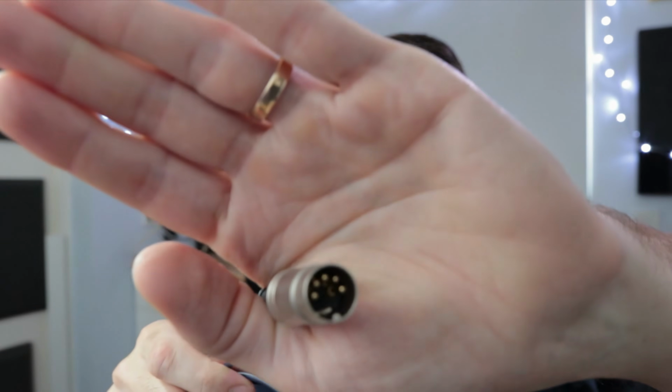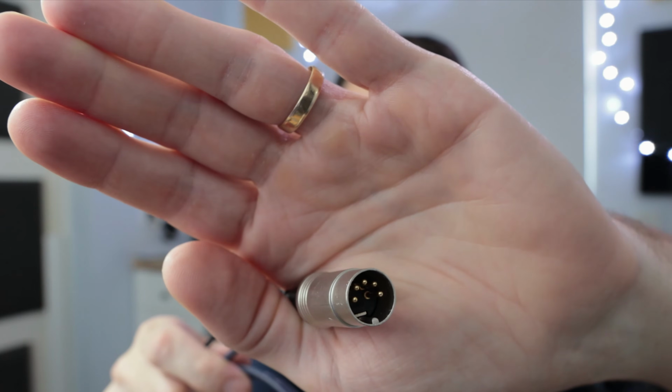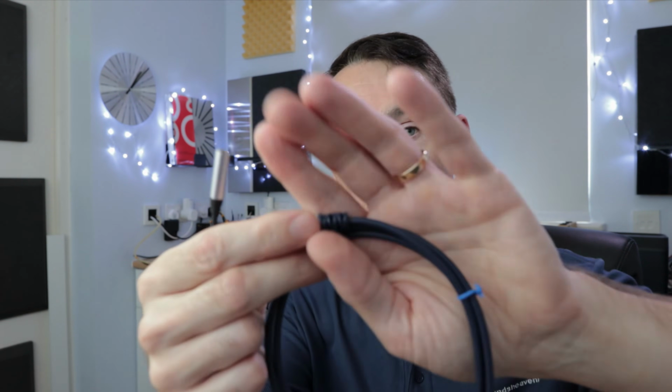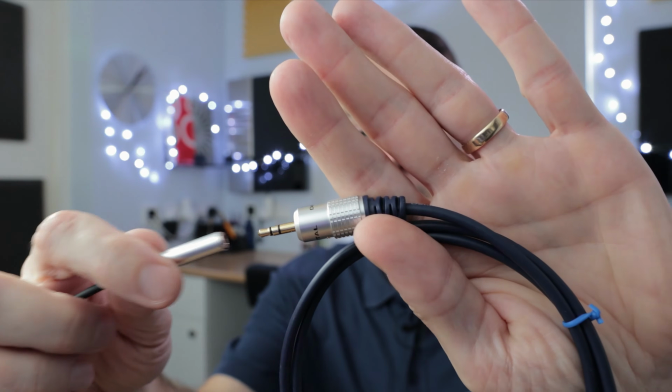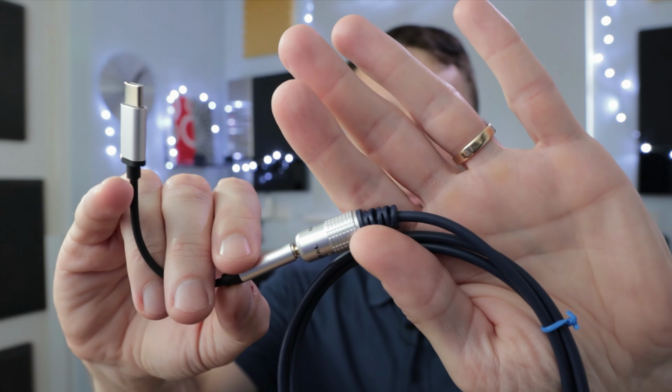So one of the most popular options for connecting is a classic Bang & Olufsen Beosound or Beosystem music player. So for example, Beosound 9000, Beosound Overture, Beomaster 5, anything with Powerlink outputs. And in that case, we'll connect a DIN plug to one of the Powerlink outputs, turn up the volume on the Beosound to around 50%. The speakers will connect to the theatre instead of to the Beosound, and then what will happen is this 3.5mm plug goes into the USB adapter and into the input of the theatre.